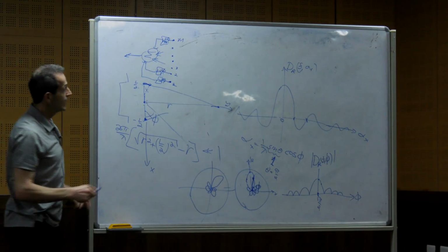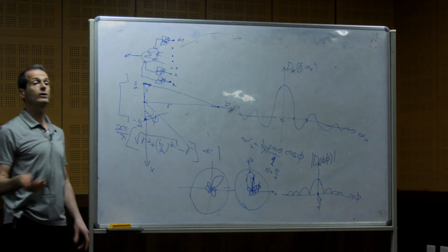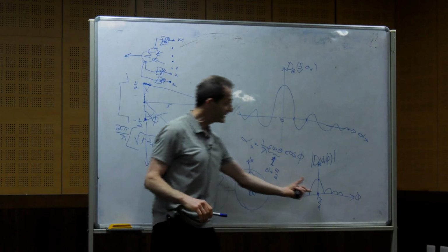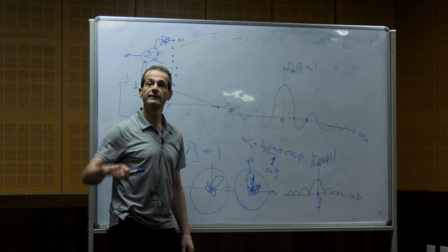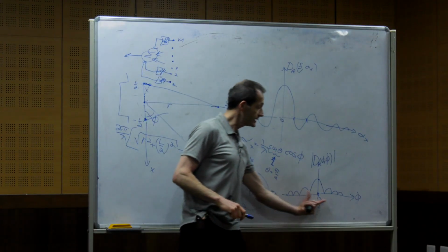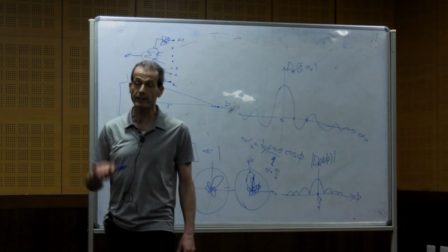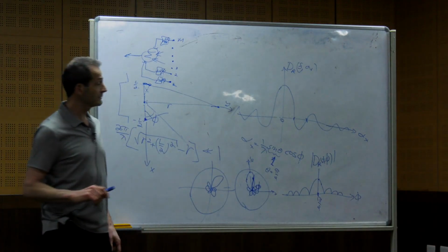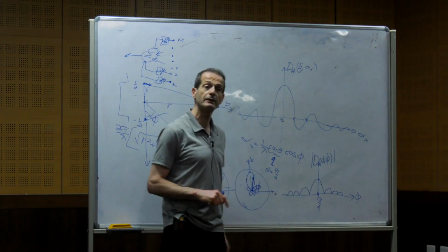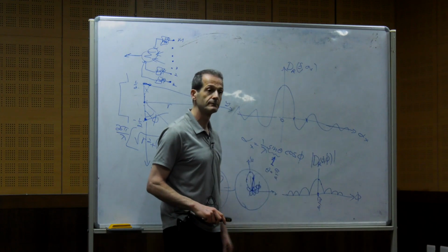Okay? So actually the design of these weights is called beamforming. Why? Because with beamforming, I can design a desired directivity pattern. The simplest way is just steering, to move it so the maximum is in a different direction. But maybe I can also change the directivity pattern such that the side lobes are lower.